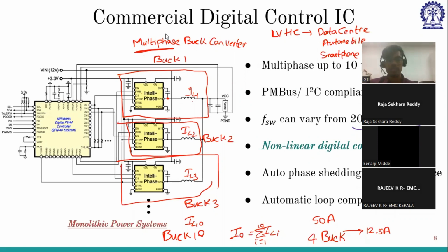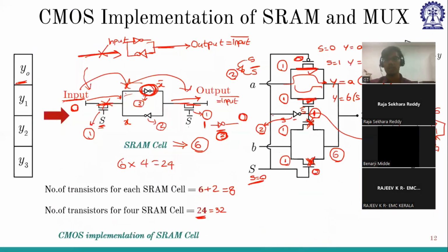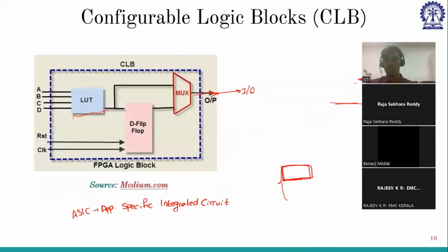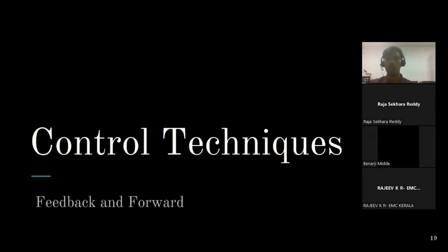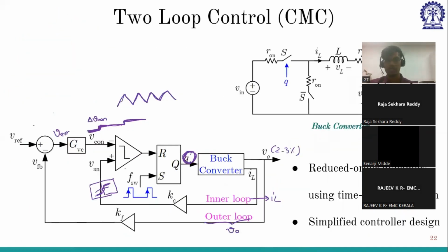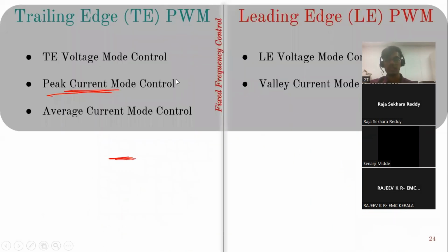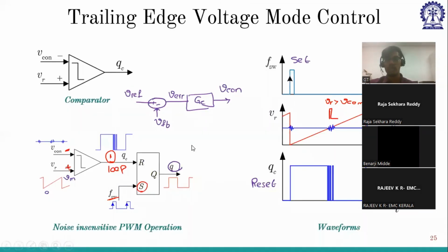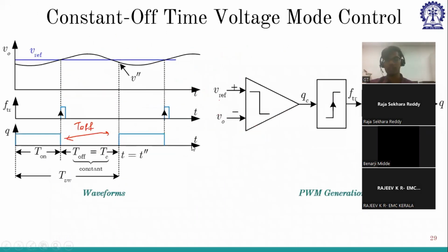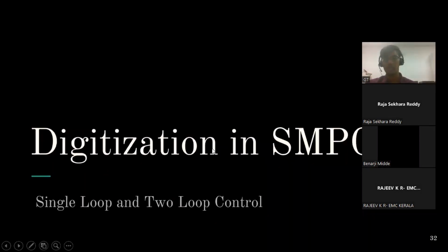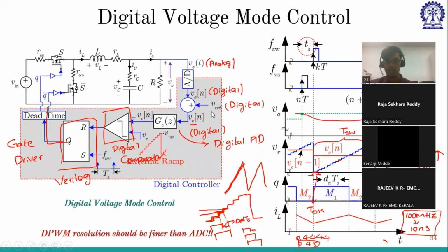Okay. And someone is asking, sir, does this code help to understand the digital control of DC to AC converters too? No, we are only discussing DC-DC converters, and the hardware results that Sarah has shown are limited to buck. But whatever control aspects we are discussing can be applicable to DC to AC. There might be some difference in the modulation technique, but the overall concept remains the same. We are only discussing digital control and how it is being implemented. For your application, maybe this architecture will change, but the implementation, the Verilog coding, everything will remain the same.